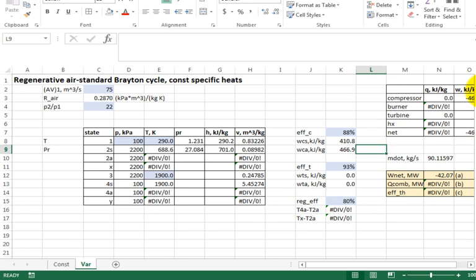Okay, well, let's press forward now because this is the actual work. So guess what? At state 2 actual, it's really the enthalpy we calculate. So this is a little tricky, isn't it? It was first temperature at state 1, then state 2s was P_r, and now h is what's used to calculate 2 actual. So we come over here and ask, what is that actual enthalpy? It's the inlet enthalpy plus the actual added work per unit mass. And so that's our actual exit enthalpy. If you wanted to, you could calculate that actual P_r. It's not needed. It would be confusing. Let's avoid it.